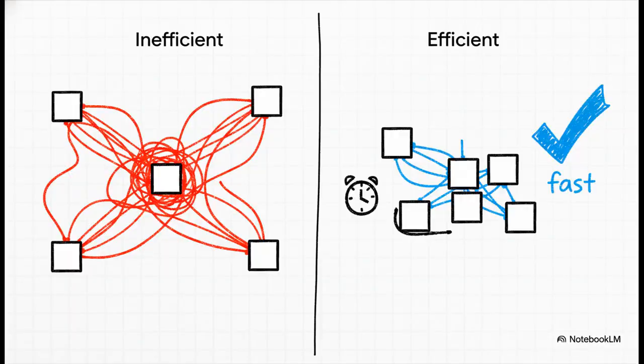So what's the number one goal for the software doing all this placing? It's actually pretty simple: efficiency. The main objective is to minimize the total length of all the wires. Just think about it. If you place 2 buildings that talk to each other all the time, right next to each other, you shorten the commute, right? And in a chip, a shorter commute means less delay, less power consumption, and a faster city overall.